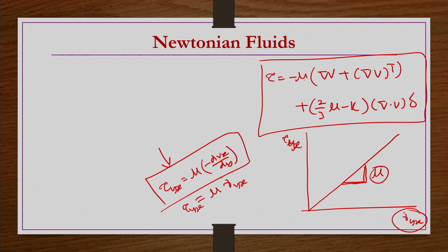And even if you shear it for a longer time or a smaller time, whatever the time that you do, as long as the temperature and pressure are constant, this curve is not going to change, and such fluids are known as Newtonian fluids. Right. So, in terms of other characteristics also, we have a number of characteristics for these Newtonian fluids, those we are going to see now.